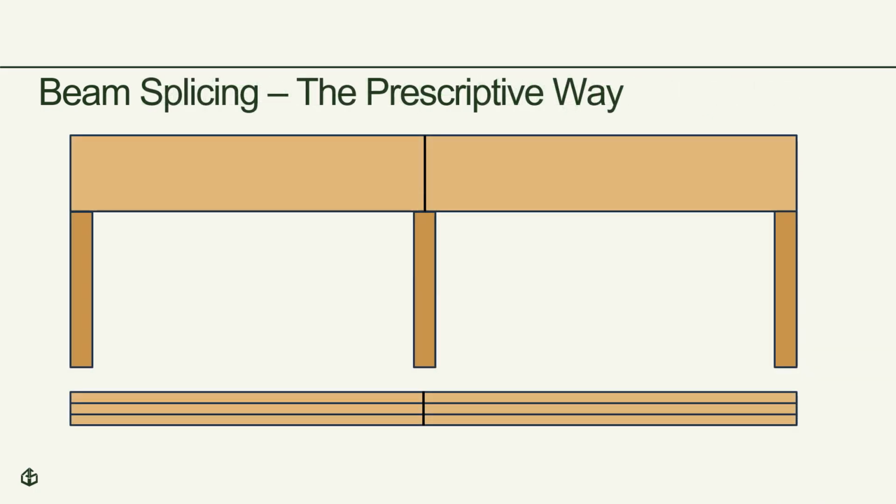When a header is required over adjacent openings, it's important that it is constructed so that each member is oriented as a single span, meaning that each individually has code-prescribed bearing and it does not run continuously across more than one opening. This is because members spanning multiple openings will experience a great amount of compression at the mid-support, which can cause the members to buckle. It's important to understand that only single spans are accounted for by the prescriptive tables, so any multi-span headers require engineering.